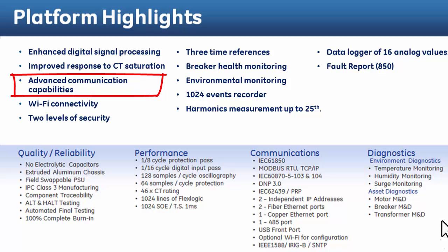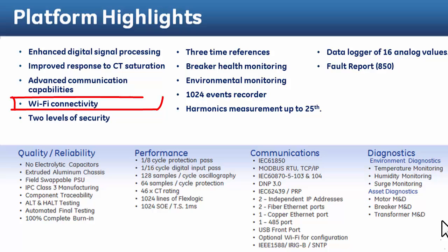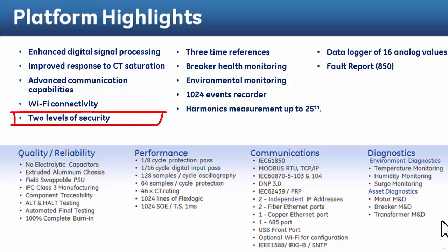Advanced communication capability, which includes support of Modbus, DNP3, IEC 61850, IEC 62439, IEC 60870-5-103 and 104, Parallel Redundancy Protocol, PRP, and IEEE 1588 Precision Time Protocol. Wi-Fi connectivity minimizes system configuration and provides simplified connectivity during commissioning and diagnostics.